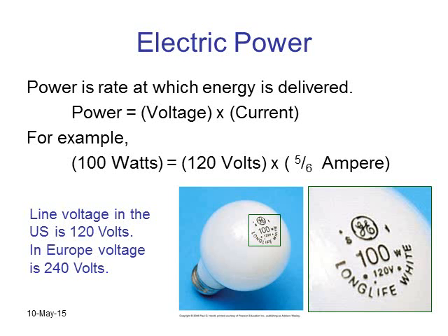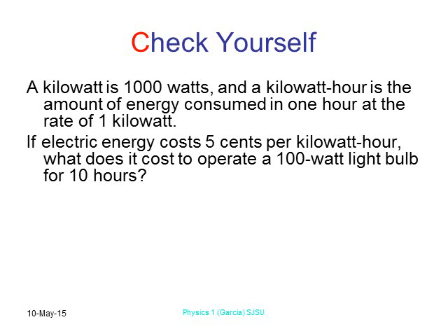Okay, power. When we talk about electric power, now we're getting into watts, and everyone has heard watts or kilowatts, or you look on a bulb and you know that it's a 100-watt light bulb. A watt is the voltage times the current. It's how much energy, how much of a drop off each electron has, times how many electrons there are, the current itself. How many of these electrons do you have flowing? And that'll give you your total power. Okay, and that power is in watts.